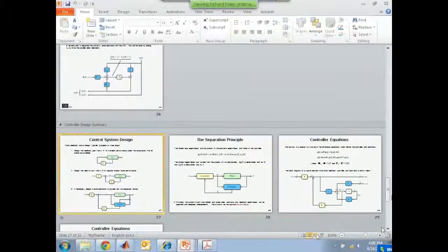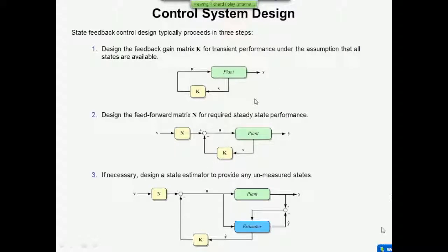If it's not exact, well then, the estimate of the state will be incorrect, and there will be errors in the control loop, which will mean you'll have imperfect control. Now, those errors are steady-state errors, principally, and so if you're employing integral control, if you're lucky enough to be able to do that, because you've got the right geometry between the correlation between the inputs and the outputs, you can take account of that, but your control will be compromised somewhat. There's no doubt about that.